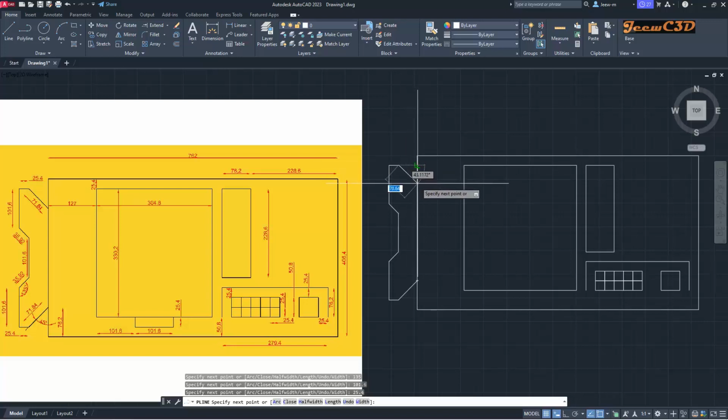and coming downward with an angle. This angle is 45 degrees downward. If you see the geometry, you can identify that one. So I will have a length of 71.84. I will type the length first this time, and I press tab key and type my angle as 45 and press enter. Now your object is finished.